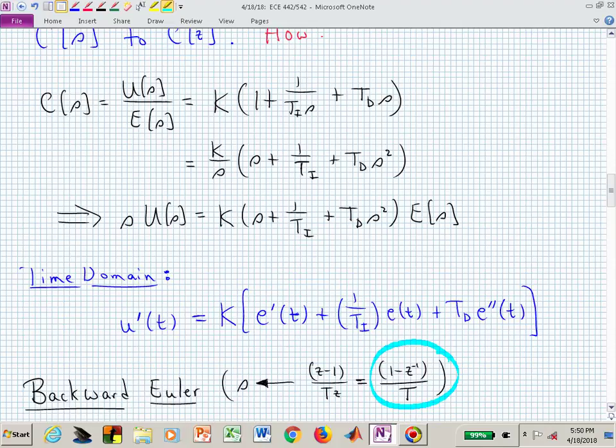And that's basically equivalent to this in the time domain, this s, and what's multiplication by s in the time domain? Derivative. So does that make sense? We're now going back to the very beginning of your calculus class and saying, how do you approximate a derivative? Oh, you take the current value minus a small variation in that value and divide by the time separation between those. That's all that we're really doing with the backward Euler.